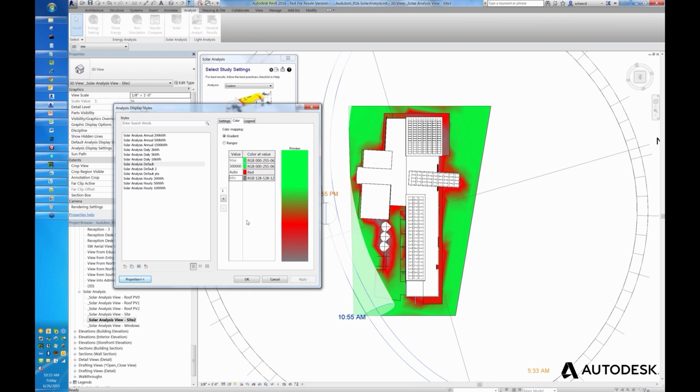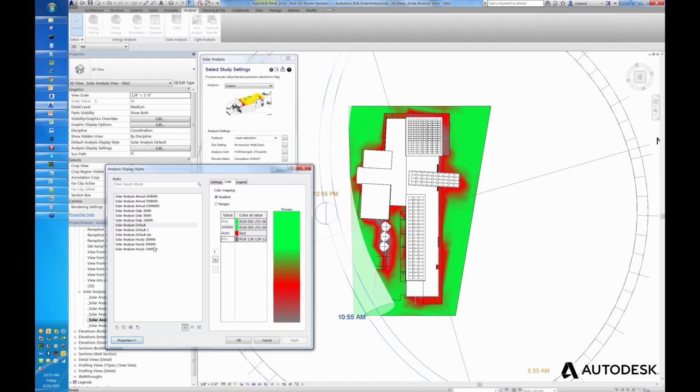Yeah, that's a good point, Tobias. Under the hood, Revit and FormIt employ the same algorithm calculations, but FormIt hard codes or wraps it into two workflows. Revit really gives you the full spectrum of customizability of what you want to see, different periods to look at, different hours of the day to look at. There's really a great deal of flexibility in there that makes this worthwhile to look at in more detail in Revit.